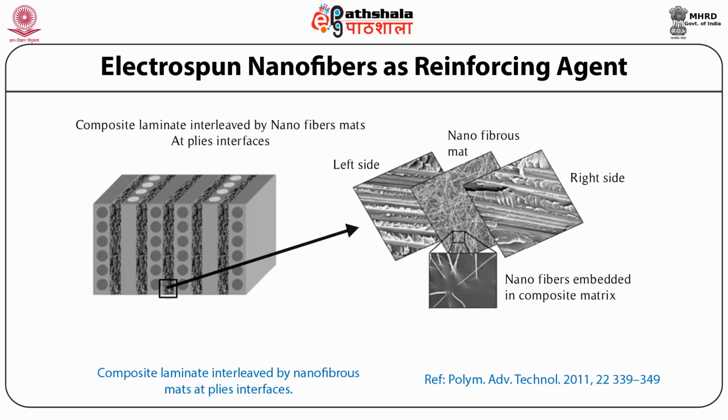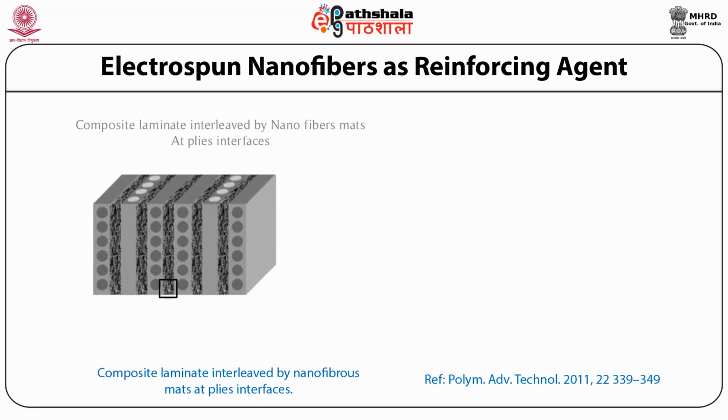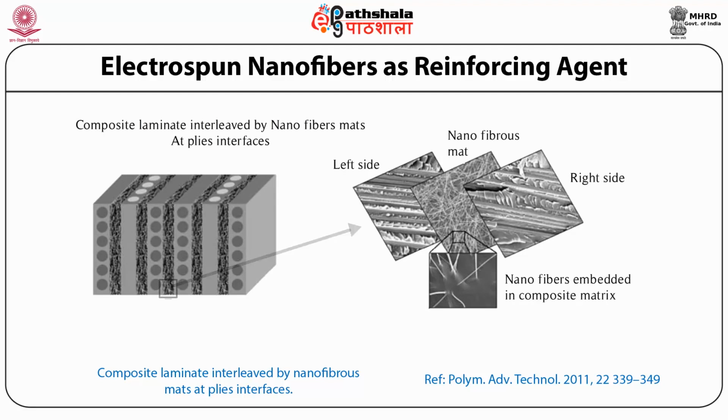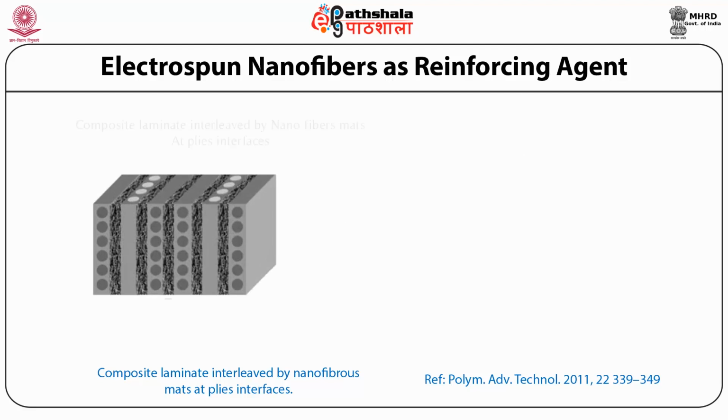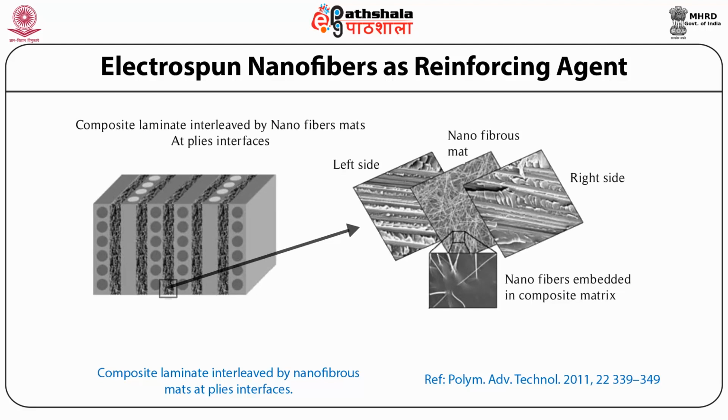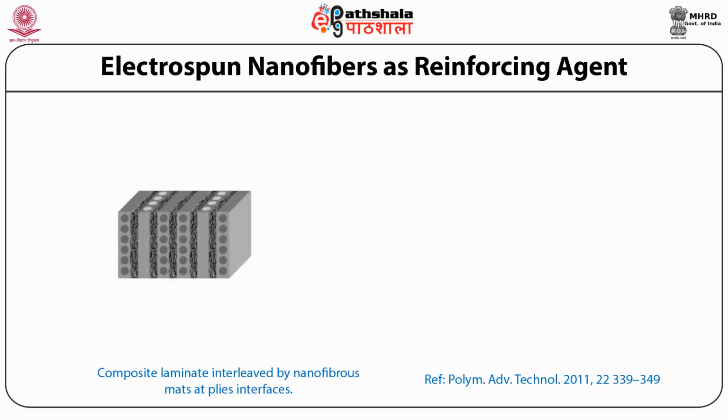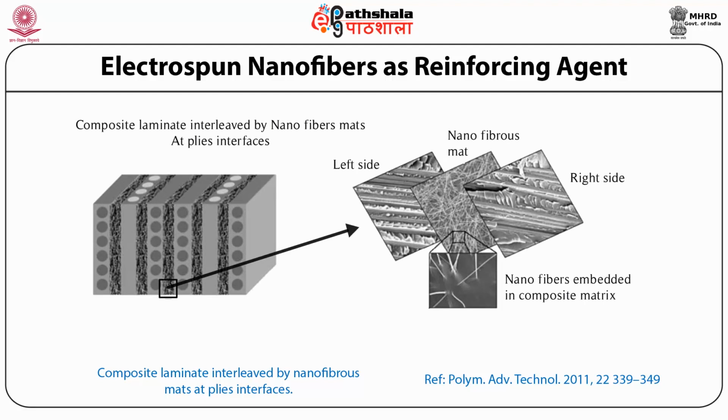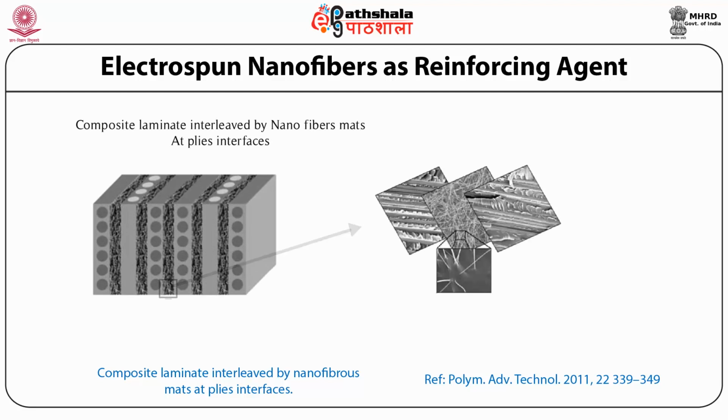The idea of using nanofiber to reinforce small-scale places, such as the regions at the interfaces of laminated composites, arises from the consideration that in such composites, structural failures mainly occur in a small critical area, in particular in matrix-rich microvolume, where the matrix is not reinforced and is experiencing high stress concentration.